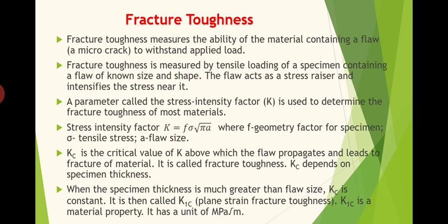The fracture toughness is measured by tensile loading of a specimen containing a flaw of known size and shape. So if we know the size and shape of the crack within the material, the fracture toughness is measured by tensile loading of that particular specimen. Okay, the flaw acts as a stress riser and intensifies the stress near it.